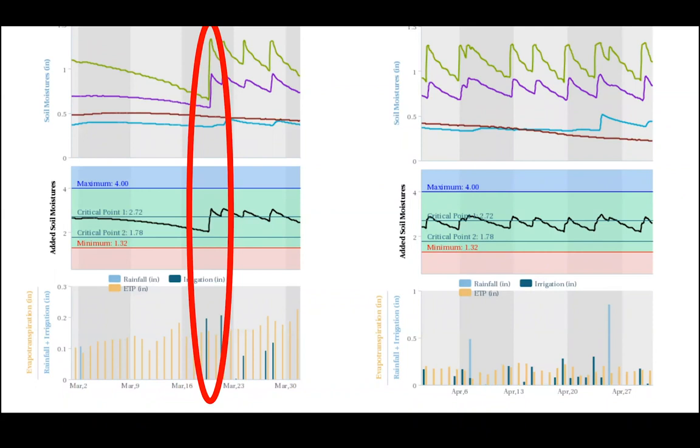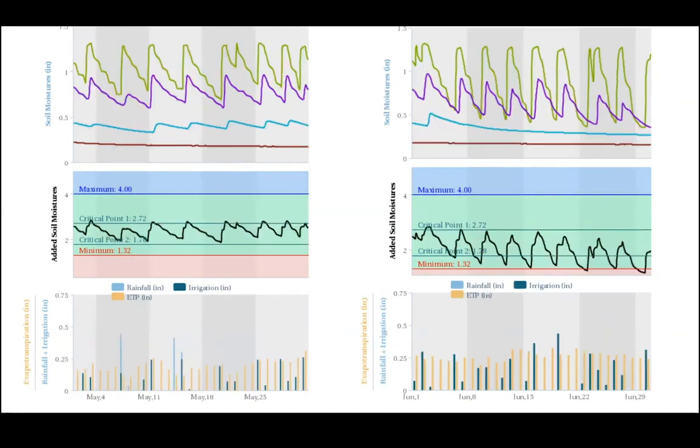And then he started irrigating based on this methodology and this duration and frequency that I explained before. And we were keeping the water very good at 3 levels, all the way down to the 3rd foot. The year before, we had seen how in June that 2nd foot had completely dried out. So in the beginning, we were keeping the water all the way down to the 3rd foot, keeping that water level up.